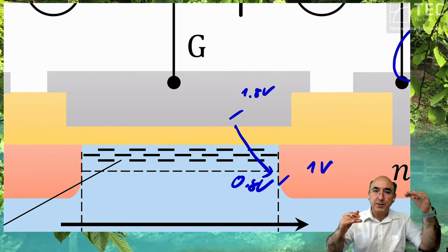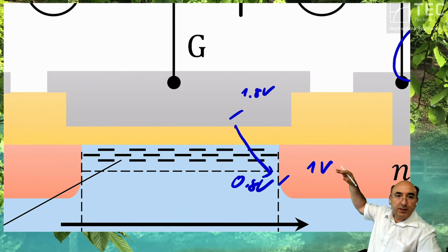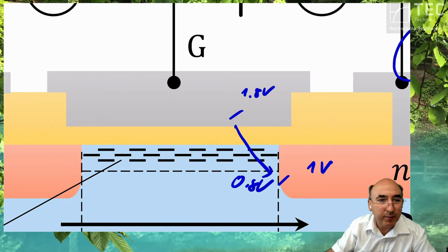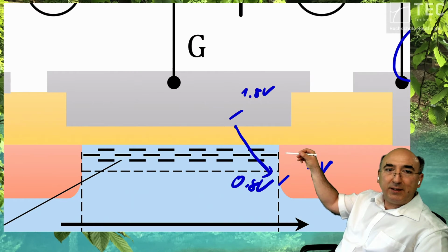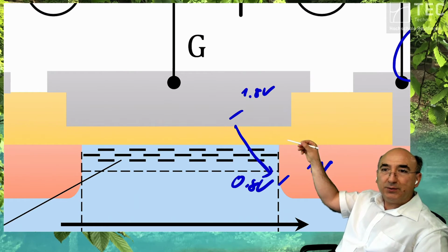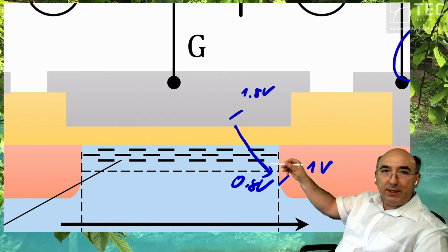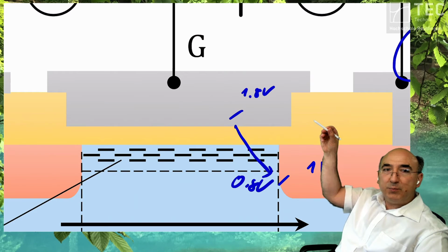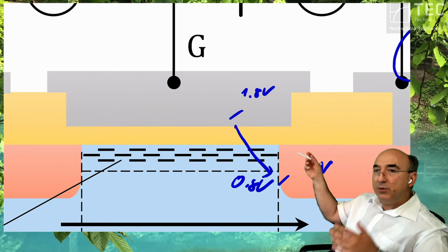If you higher up your leg, you squeeze the potential. One moment, I have to increase my picture. Here I am. If I increase my leg, then I squeeze this potential difference. And if this potential difference between metal and this doped area is lower than 0.8 volt, then you have no channel.